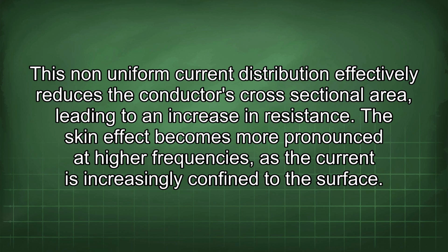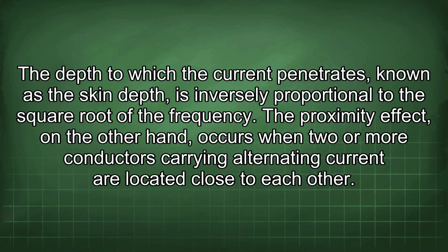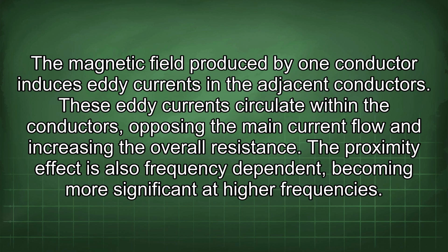The skin effect becomes more pronounced at higher frequencies as the current is increasingly confined to the surface. The depth to which the current penetrates, known as the skin depth, is inversely proportional to the square root of the frequency. The proximity effect, on the other hand, occurs when two or more conductors carrying alternating current are located close to each other. The magnetic field produced by one conductor induces eddy currents in the adjacent conductors. These eddy currents circulate within the conductors, opposing the main current flow and increasing the overall resistance. The proximity effect is also frequency dependent, becoming more significant at higher frequencies.